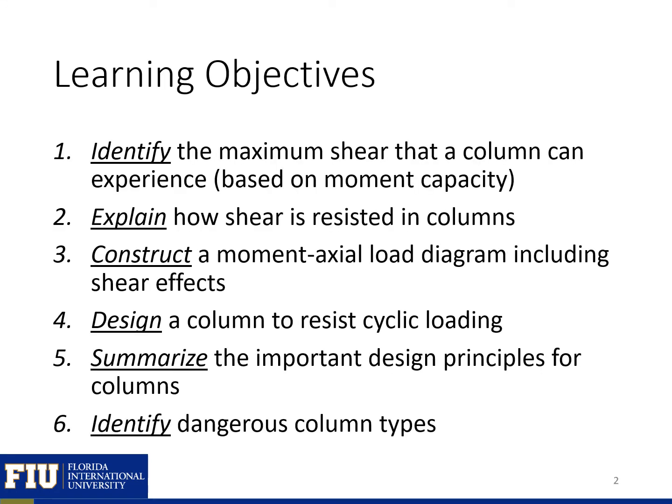By the end of this presentation, you should be able to identify the maximum shear that a column can experience based on moment capacity, explain how shear is resisted in columns, construct a moment axial load interaction diagram that includes shear effects, design a column to resist cyclic loading, summarize the important design principles for columns, and identify dangerous column types.